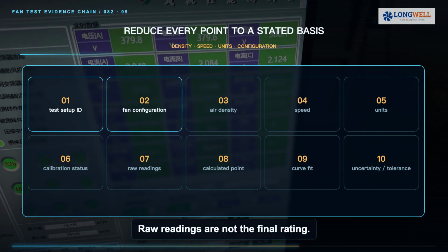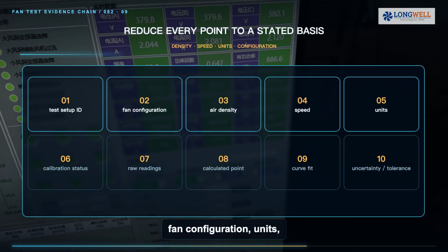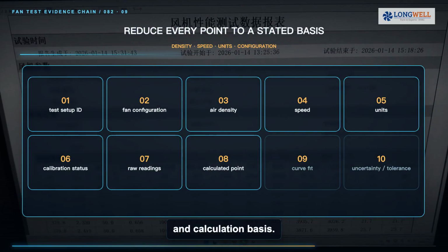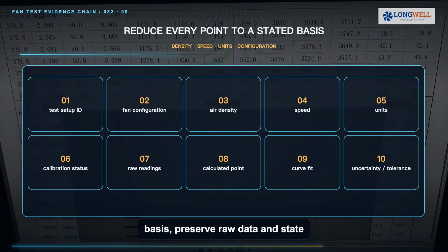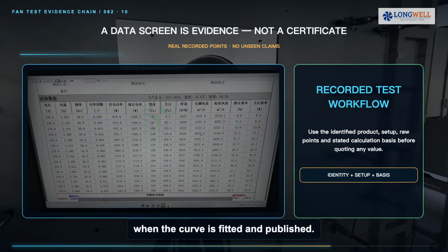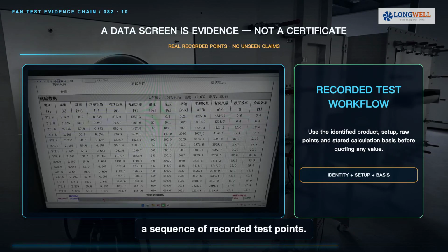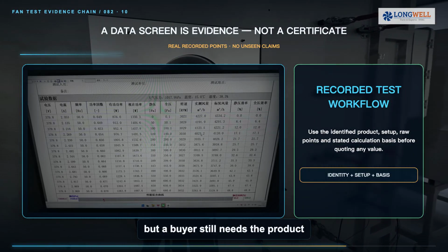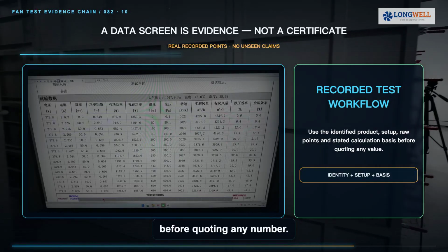Raw readings are not the final rating. Record the exact setup, fan configuration, units, density, speed, calibration status, and calculation basis. Reduce every point to the declared basis, preserve raw data, and state the tolerances or uncertainty used when the curve is fitted and published. This real longwall data screen shows a sequence of recorded test points. It is valuable evidence of workflow, but a buyer still needs the product identity, setup drawing, raw readings, and calculation basis before quoting any number.